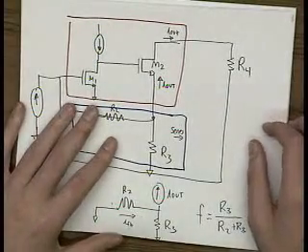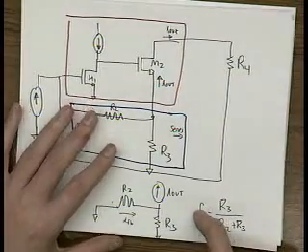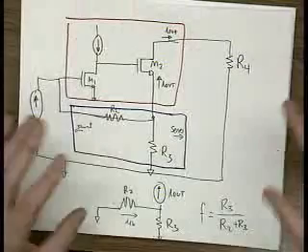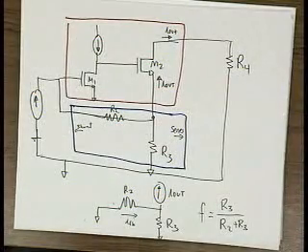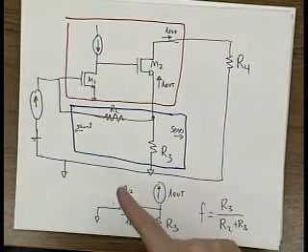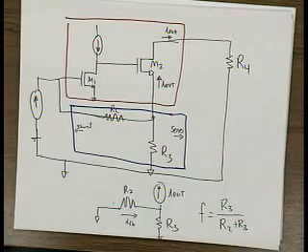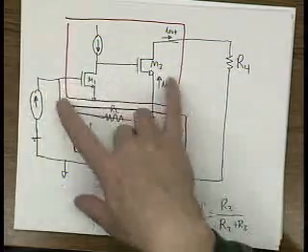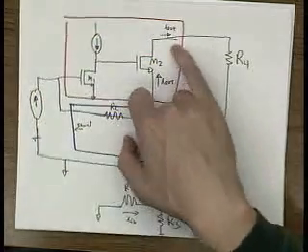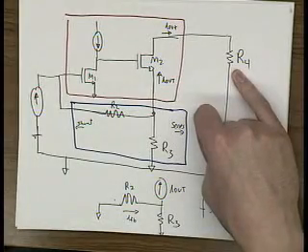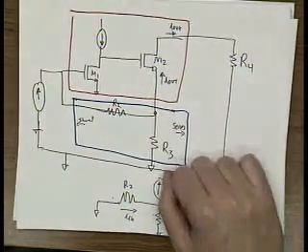Okay? So basically, you can calculate the feedback network. You can calculate the forward loop gain, and then from there, calculate what the overall gain is. And because this is a series feedback, the gain will be unitless. It'll be current in, current out, and then multiplied by R4 to get the voltage out. Okay? So that's it. Any questions?